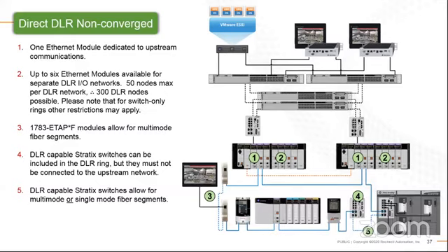So that could be your segregation method based off the converged plant-wide Ethernet design that we put forth on how you do that separation, potentially via VLANs, the different switches, different systems, maybe a DCS versus the motor control center, things of that nature.